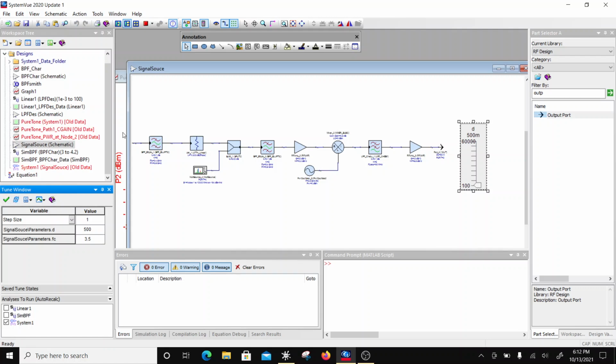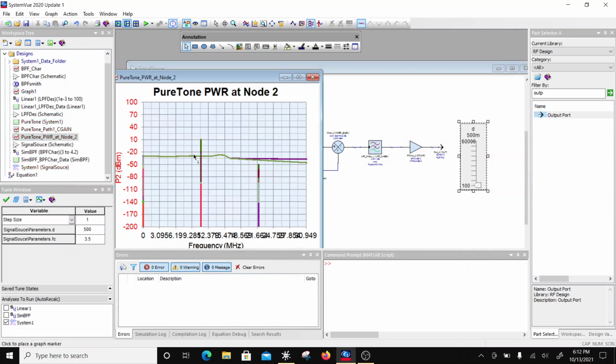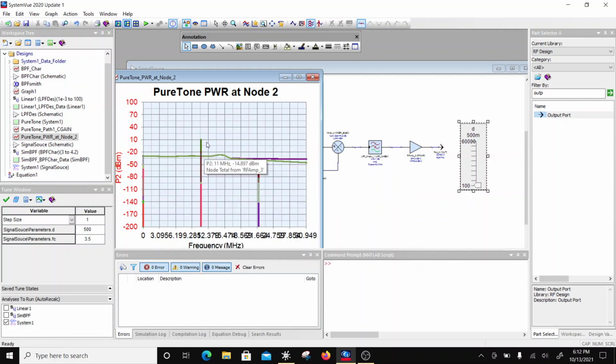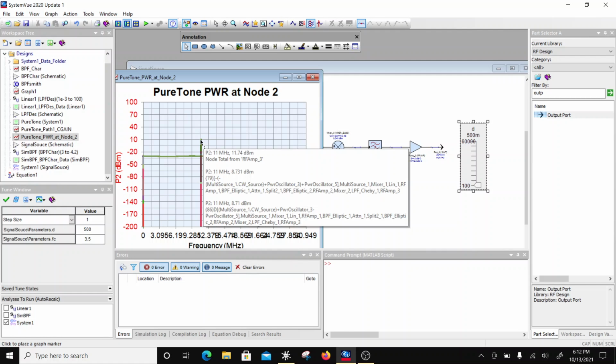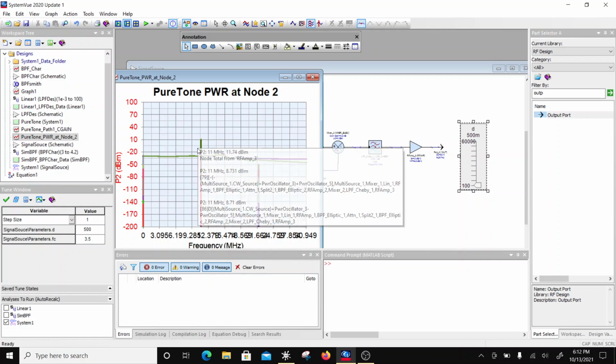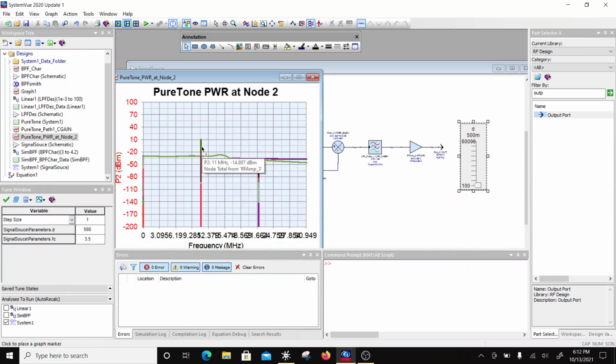So that's a half a kilometer, and at half a kilometer I'm putting out 11 dBm. Okay, so at half a kilometer my detector is seeing 11 dBm of power, which is going to be a voltage swing of around more than 1 volt on the ADC. So you understand, you have to have this in the dynamic range of the ADC.